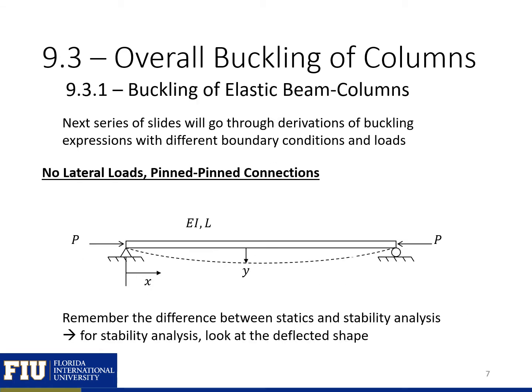On the next couple slides, we're going to go through some derivations of different buckling expressions with different boundary conditions and loads. Some of these equations are actually found in the code, so you don't necessarily need to know the derivation, but you can see where some of these equations come from. A lot of these things are taken from different stability courses. Just remember that the difference between statics and stability analysis is that for stability analysis, we're going to look at the deflected shape, where in statics we looked at the undeflected shape.